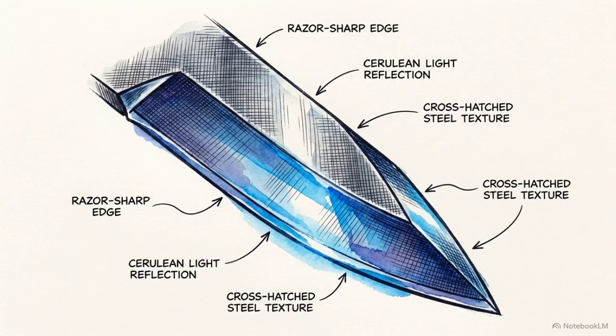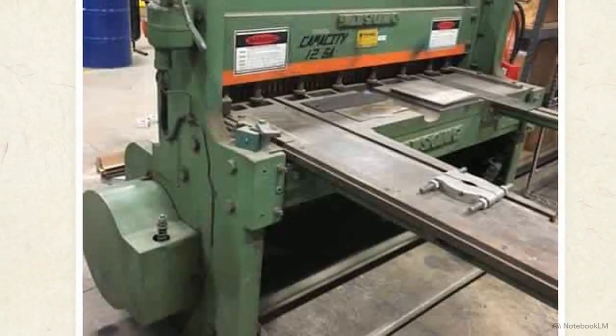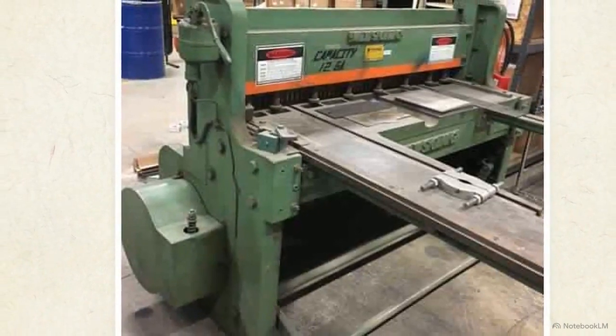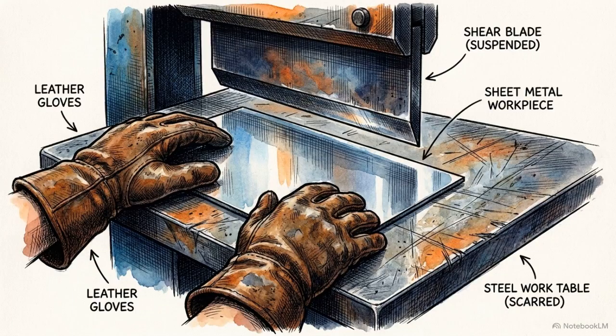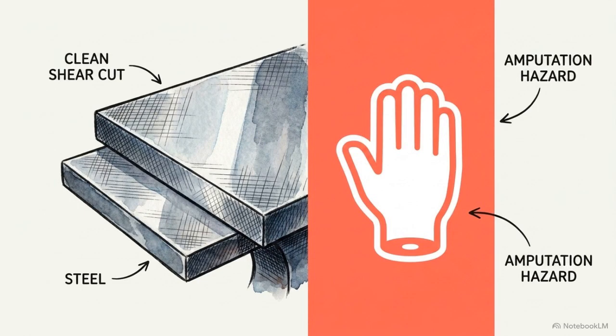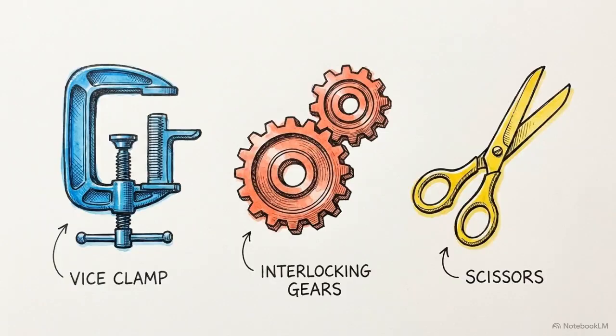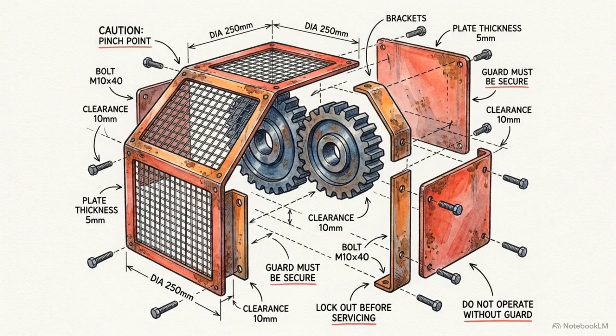The final primary hazard category relies on cutting rather than crushing. This is shearing. Shearing involves power-driven blades designed to slice through high-density materials like metal, plastics, and industrial composites. If an operator reaches under that descending blade to place material or make an adjustment, the machine will process a human hand with the exact same ease it processes sheet steel. Correctly identifying whether a machine crushes, nips, or shears is the strict first step. Without isolating the exact kinematic action, you cannot design an effective physical countermeasure.